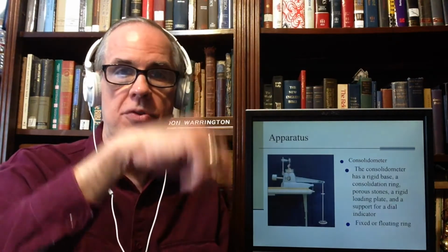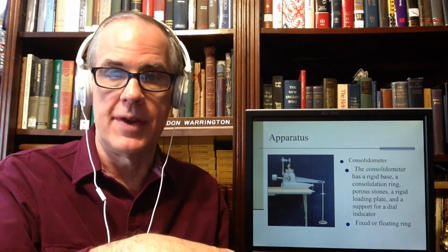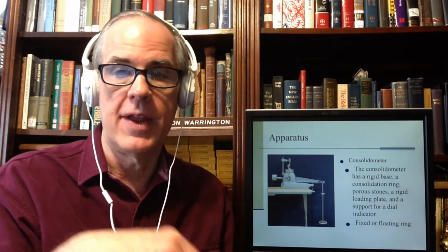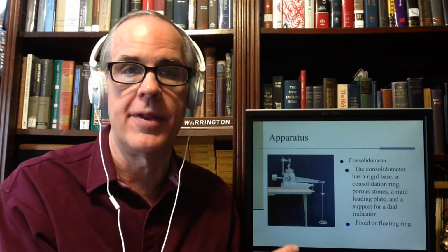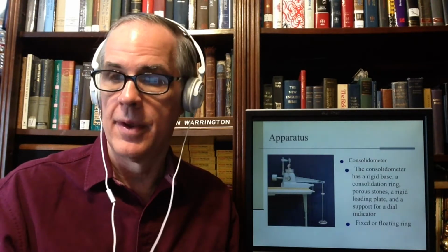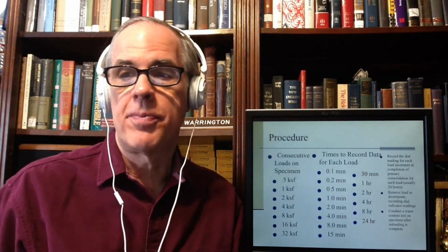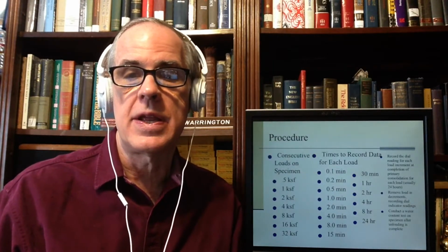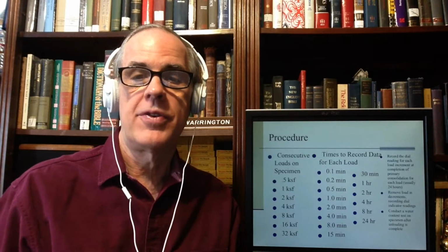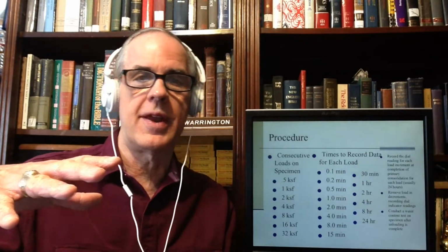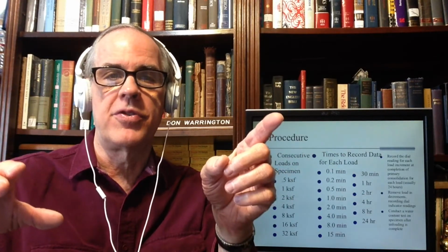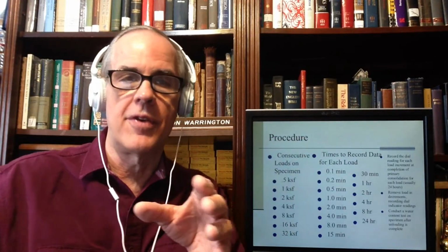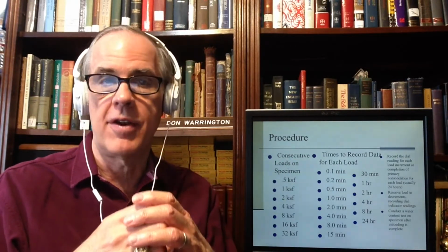Newer ones use sometimes air pressure to push a piston down. The advantage of the air pressure is that you could actually run the test completely remotely without having to run in every 24 hours and put more weight on this thing, which is the way we have done in our lab. We apply consecutive loads on the specimen, and normally it takes 24 hours per load. We take the force, do the little beam thing in statics, and come up with a first setup for half a KSF, then 1 KSF, and all the way up to 32 KSF on this specimen, which is standard size.